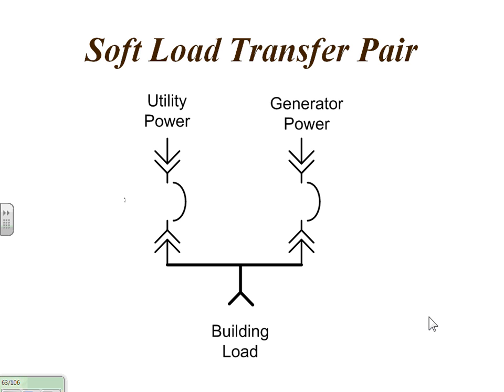There's something in the sensor that will close a set of contacts, which is going to operate the generator battery to start it. You'll have a normally open contact that, as long as we have power from the utility, will be open. The minute that we lose power, like you said, it closes to start the signal for the generator. It gives the go signal. Good point. Good question. Anybody else?